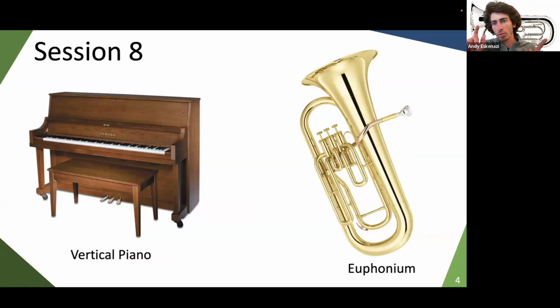We're going to learn how to create equations, or really how to create parameters, for example, height and width. Then we're going to explain how we can bring those into our CAD environment and start to use them in our specific dimensions. For instance, when I draw a rectangle to have the overall shape of the piano, I can establish that to always be equal to the height and always be equal to a width that I have established beforehand, and that will have full controlling power over our CAD design.